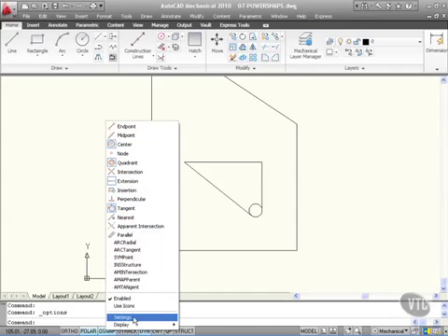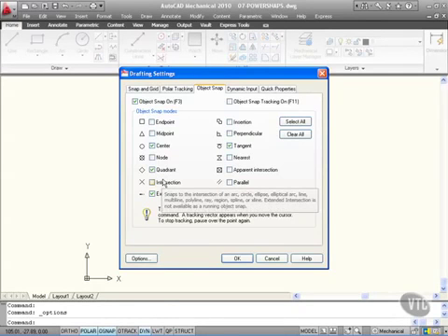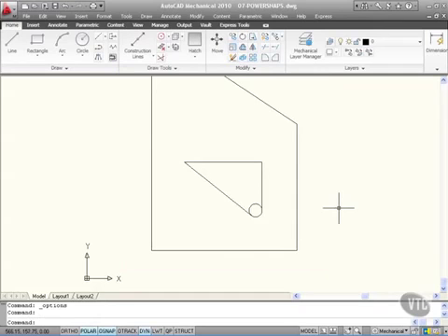If I just go to settings there, you'll notice endpoint wasn't there. That's because I'm using Power Snap Configuration 3. But obviously endpoint is one of the default snaps, so that will be there anyway. So remember that, your default snaps kick in as well as your Power Snap configuration. Hence I was able to use the endpoint snap there and there. So that's power snaps for you.